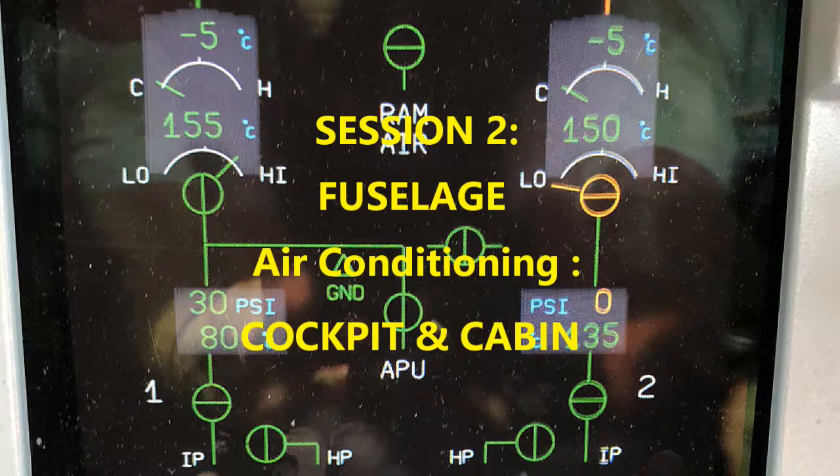So about the relays, because if there's an overheat, we have overheat thermo switches and they're operating. If the fans are going up to 320 degrees Fahrenheit, then those thermo switches are going to remove the ground from the power relays, which is going to force the fans to stop, and then those fan fault relays are going to open. When that happens, it's going to send the signal to the CFDS and also your ECAM system, letting them know it's an overheat issue. All right, so that gives you an idea there.